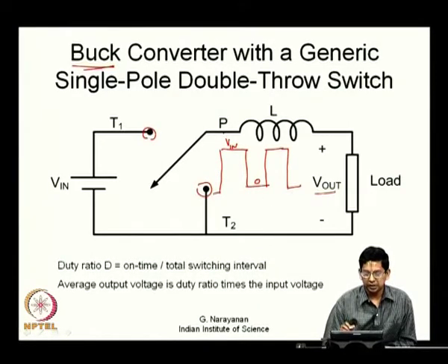So, what you get is such a pulsed square waveform. Now, this has certain average value, and this is the average voltage that we require for the load. The average voltage dropped across the inductor is 0, so the entire average goes through the load. The inductive filter serves to smoothen the current as we saw before, and we can also have an additional capacitance connected across the load for further smoothening of the current, and to smoothen out the load voltage too.